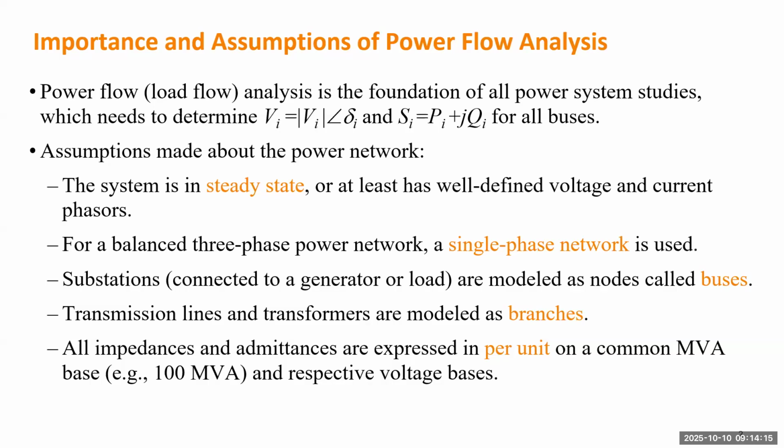For the impedance or admittance, they will be represented in per unit values, and voltage will always be around 1. So if you consider operating a system to maintain the voltage within maybe 5% deviation, the per unit value everywhere will be roughly from 0.95 to 1.05.